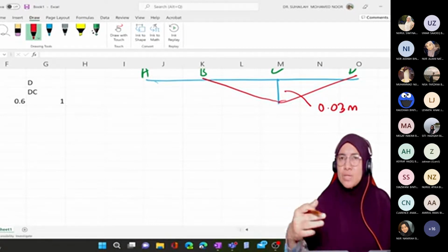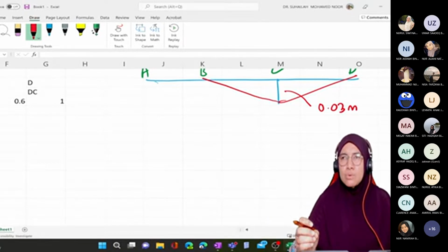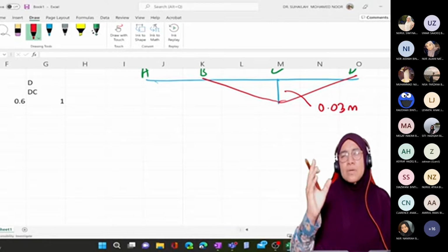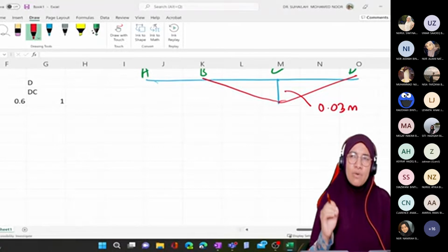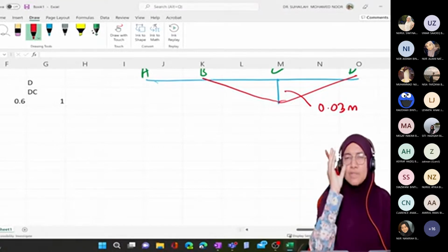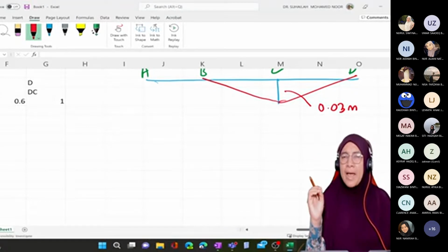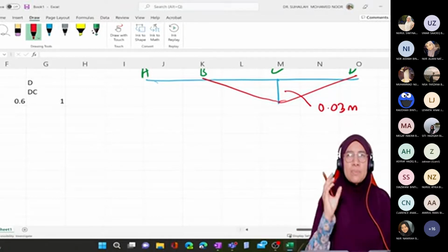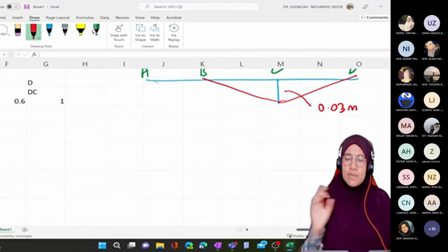But I want to show another alternative solution so that we can only refer to the first column in the formula, because in the textbook the formula for FEM has two columns. The first column is for end fix, the second column is for end pin or roller. So I have used the first column only, assuming all fixed end.